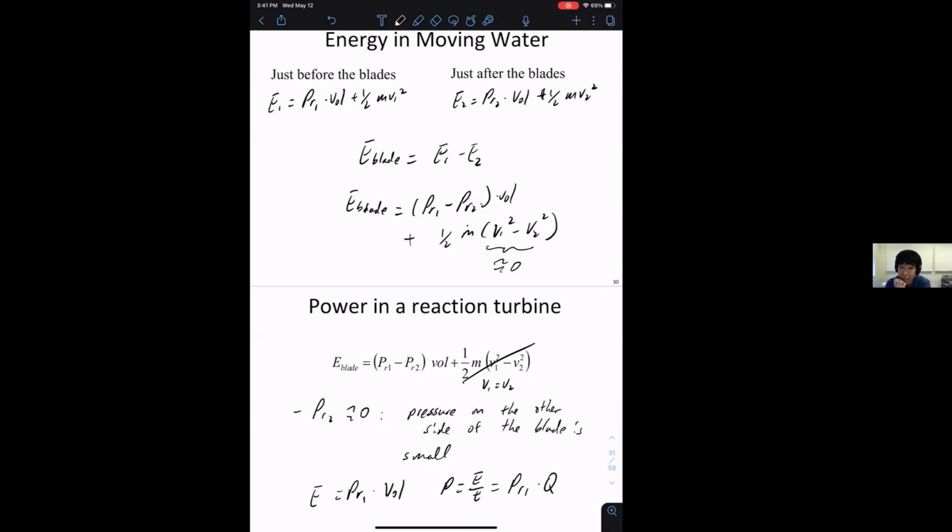When the H is low, that's sort of the only choice you have. And the impulse turbine also has many sources of loss. You have water heating it, of course, some water will bounce back and cancel each other out, you don't hit the correct target right on, things like that. So it turns out to be roughly similar efficiency.